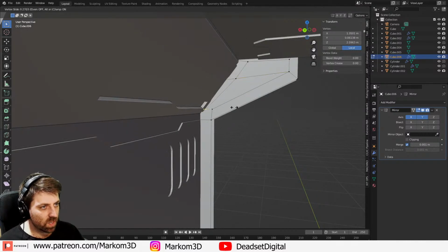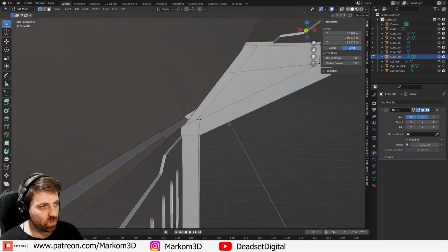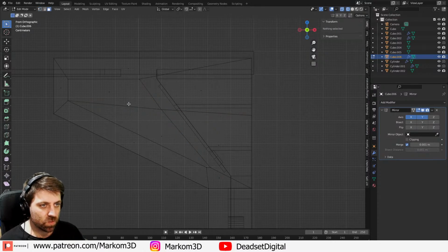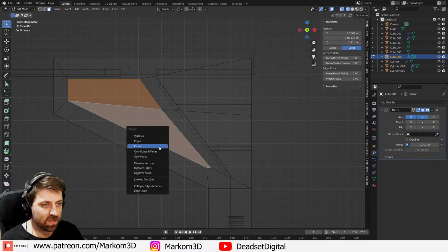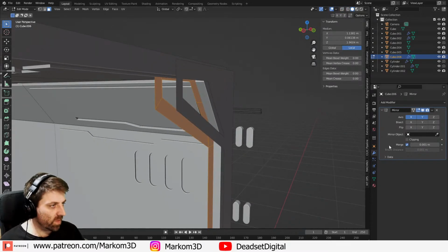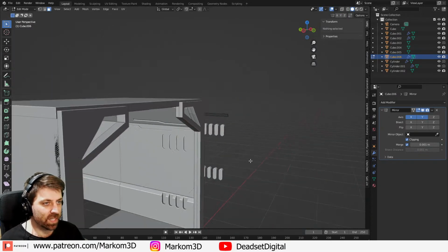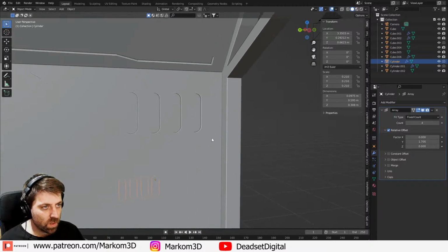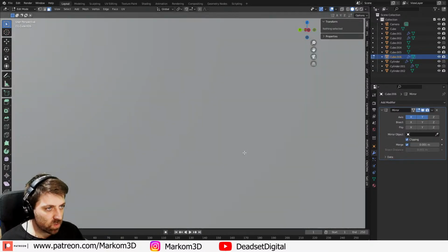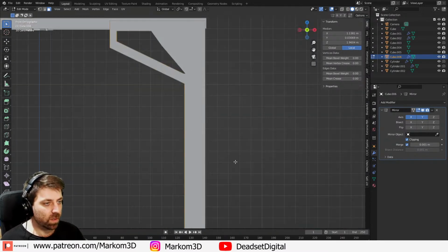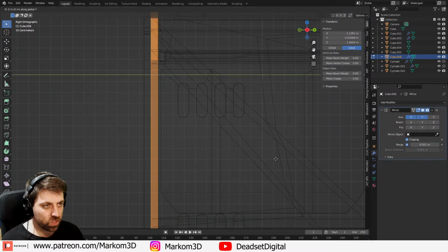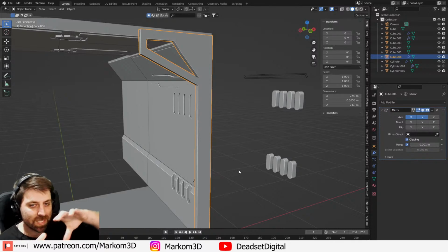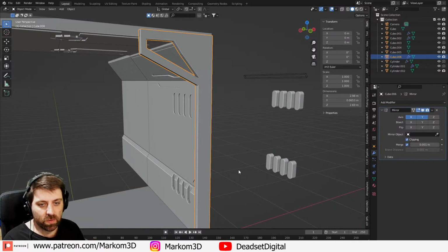And so I'm just going to line that up. We're going to try and do our best to follow the edge. That's not too bad. Let's now delete this face. Let's now grab this, turn on clipping, E to extrude, delete that internal face. So now we have this kind of barrier piece. I think that's a little bit too far out. Make it a little bit thinner. Let's go GY. Yeah, maybe something like that. And what this piece is mainly to do is to hide the seam in between all the other pieces.